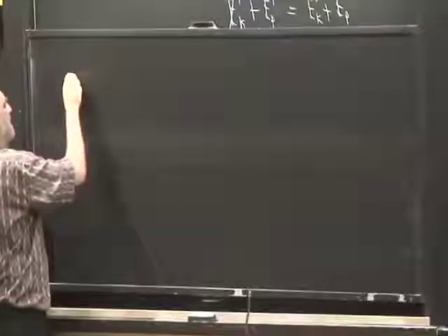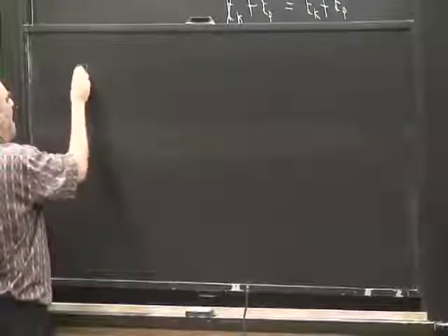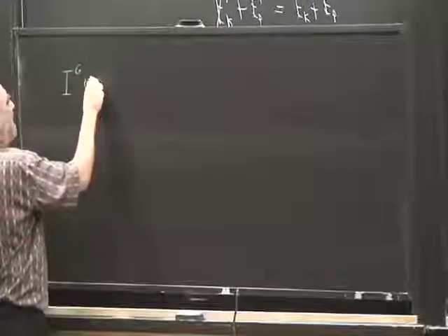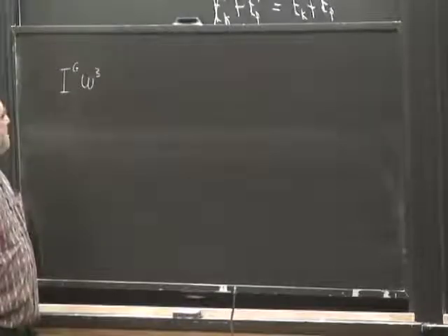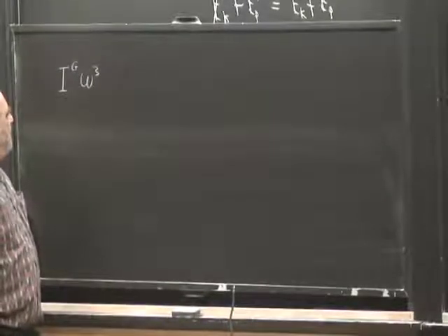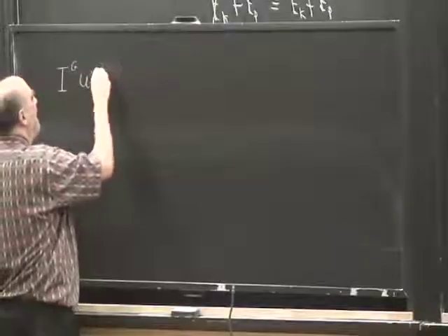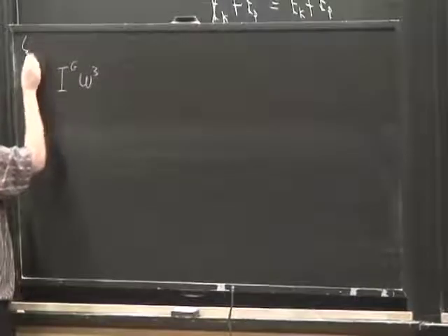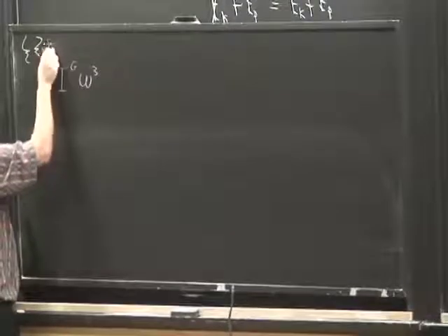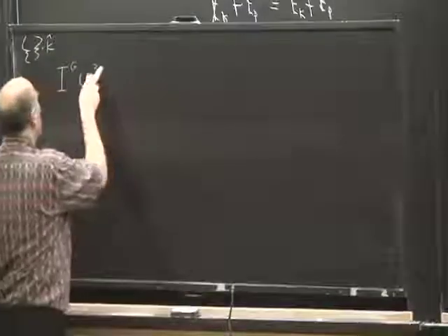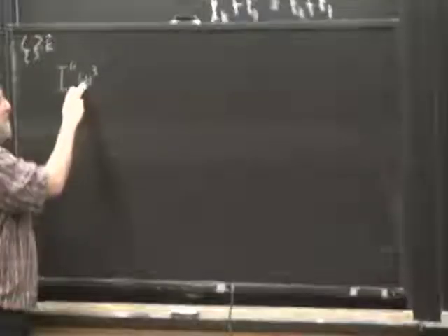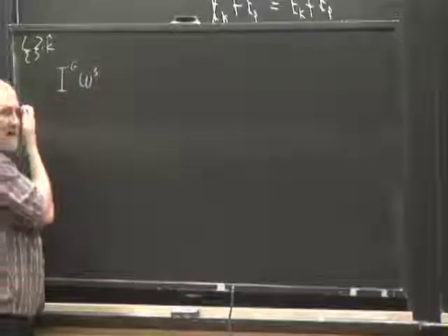Remember that we know omega_3 from the previous calculation. So we have I_G omega_3, that's omega just before the collision, and this is multiplied by k. So we're going to take that whole expression there, and we're going to take the dot product of both sides with k. This quantity is going to be a negative quantity because before the collision omega_3 is negative.